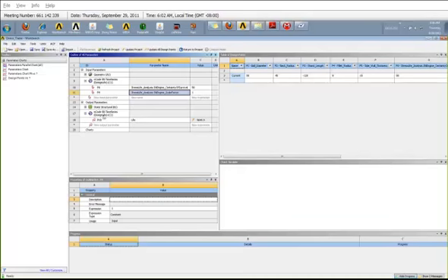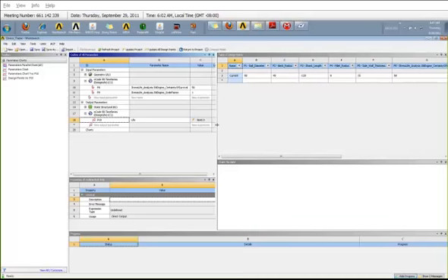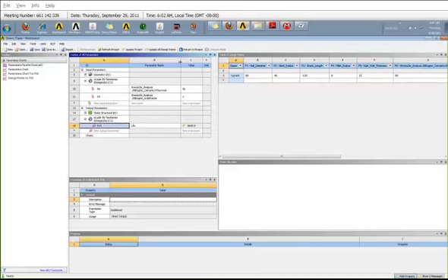and the output parameter from my DesignLife is going to be the life I'm going to look at. So if you want to set up a what-if study, you can just pretty much enter those different design points and hit update all design points, and you can look at the design points. But the objective of this demo is to do a design exploration and look at optimizing the design life.